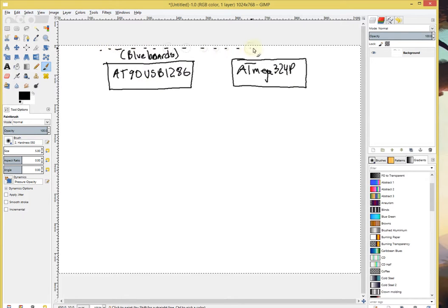That is a term that is part of the Microsoft Visual Studio IDE, upon which Atmel Studio is built. Inside of our solution, we're going to set up 2 projects. One project we'll call the target, and another project will be for simulation purposes.